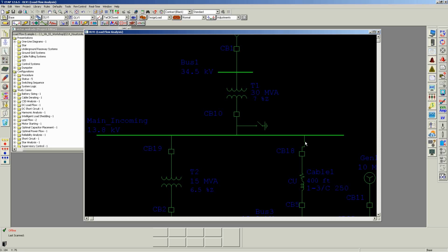Part number two is to actually enable the switching interlock enforcer. Right next to the option that is called check circuit continuity, there is a switching interlock enforcer logo. It's a little button just under your help pull-down menu. You want to click on switch interlock enforcer.